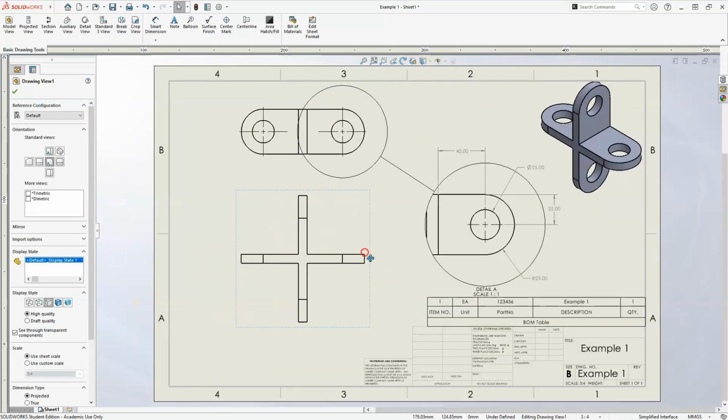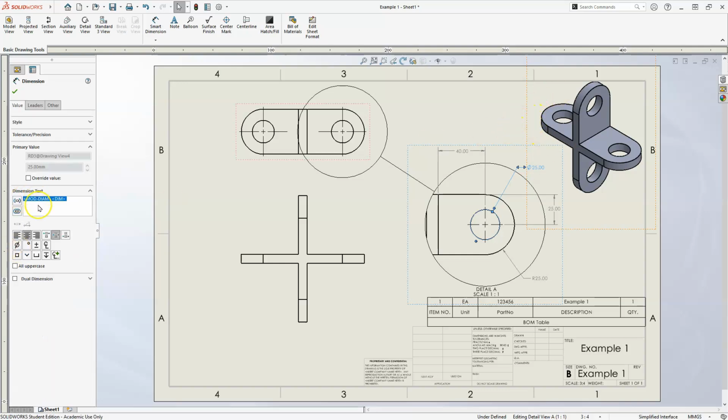We will get into doing a few more complex drawings, and we can add verbiage to here. So if this is something that you want to do, all I did is select this dimension here. Once this comes up at the bottom, you can see that this is in 4 different places. So I can add to the bottom of this 4 places. And let's go ahead and turn my caps lock on.